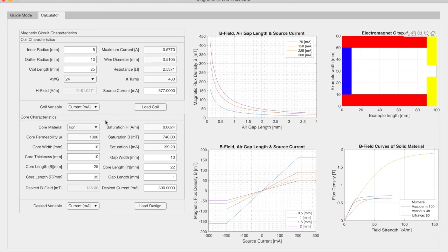So then this code behind the whole simulator will be finding the short circuit saturation current, and will establish that that's the maximum magnetic field or current that the magnetic core can handle. Then it will stop growing the response.